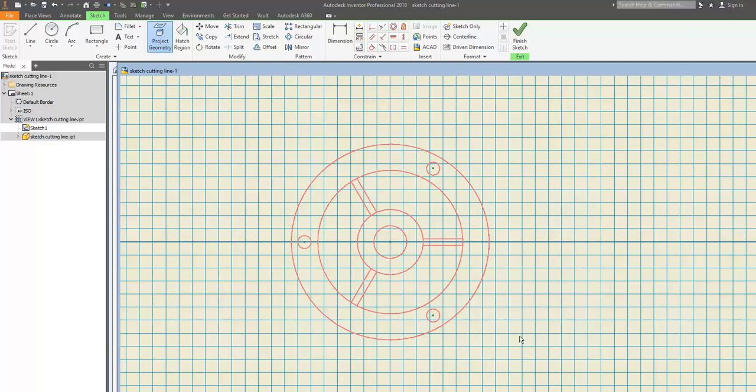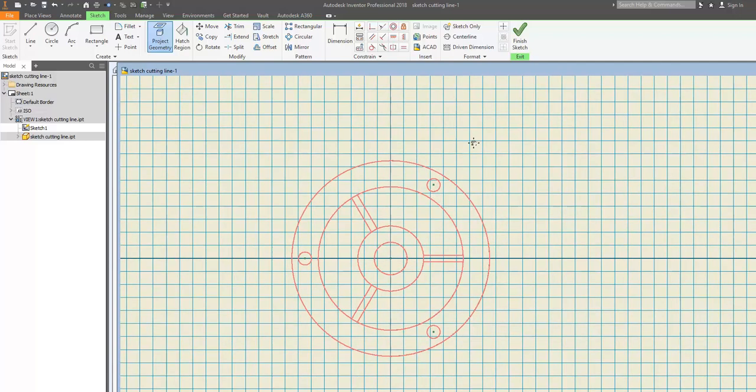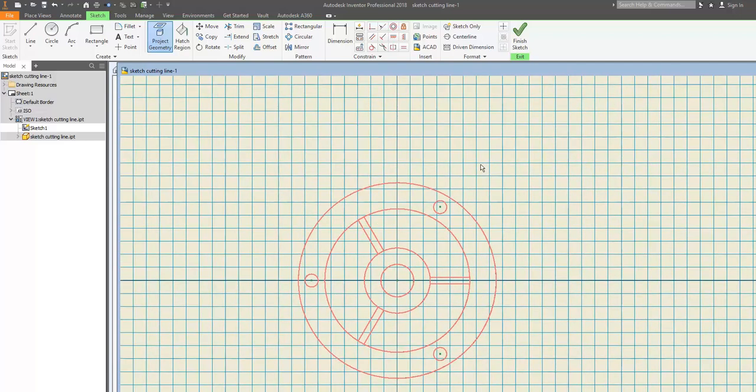Now here I want to consider this rib as if parallel. The radial axis of this hole is as if parallel to the picture plane on which the sectional view is needed. If it is the top view, and now this is the top view, then the sectional view is going to be, in this example, the front view, the sectional front view.